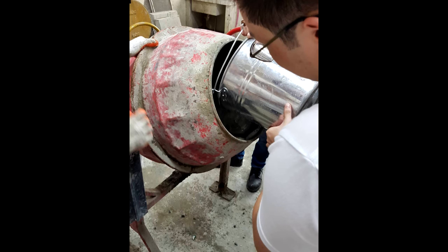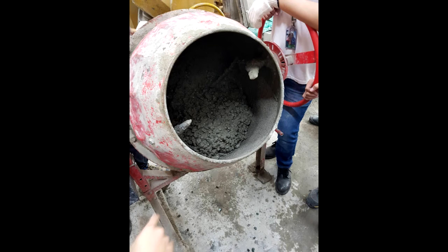Some of the materials that are added to form concrete and affect its properties are water, coarse and fine aggregates, cement paste, and other admixtures if present. The concrete mix design proportion can be based on the mass or the volume of each component. However, the water-cement ratio proportion is commonly based on the mass of the materials used in the mixture.